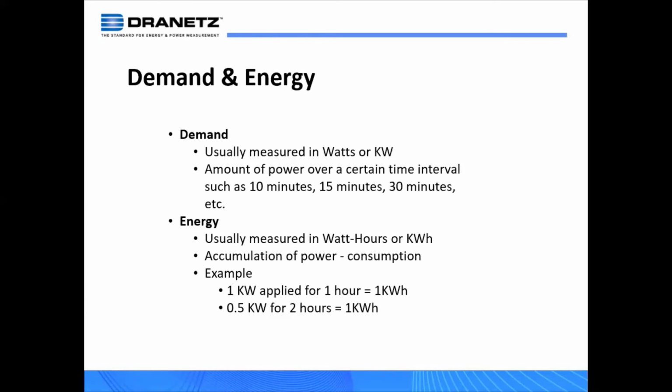Energy is pretty straightforward. It's basically watt hours, or you'll hear kilowatt hours, or you may hear megawatt hours, and it's just simply accumulation of power over time. For example, 1 kilowatt for 1 hour equals 1 kilowatt hour. So it's pretty straightforward, and if you're a residential customer, that is the bulk of your bill: kWh, kilowatt hours. Conversely, for an industrial or commercial customer, or let's say a non-residential customer, demand makes up a big part of your utility bill.